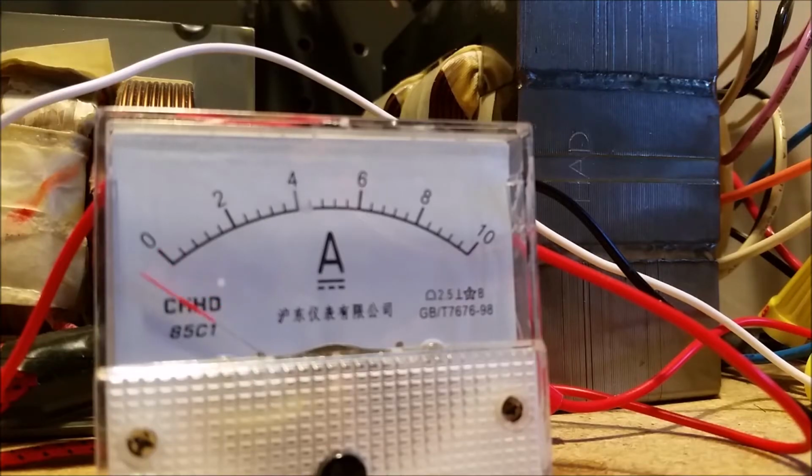You might think generating electricity this way is inefficient, and to a certain extent you'd be right, because it takes electricity to make electricity. However, keep in mind that as you increase the speed of the generator, the output power increases, while the field current stays the same. And so if you spin the generator to a certain speed, say a few thousand RPMs, you can get over 100 times the amount of power out that you put in.